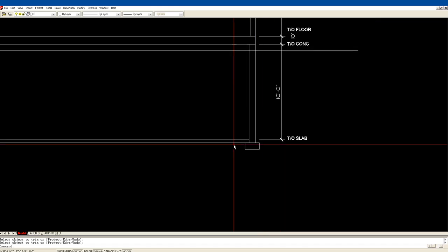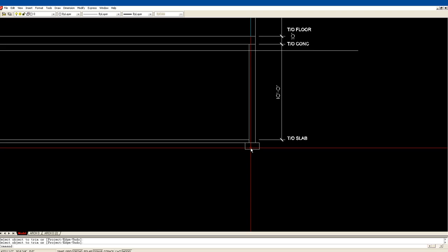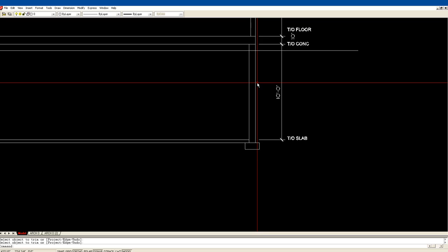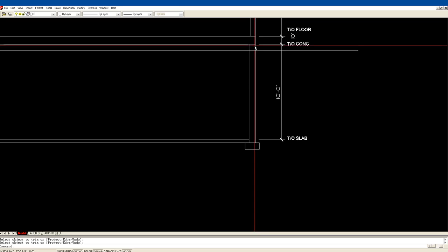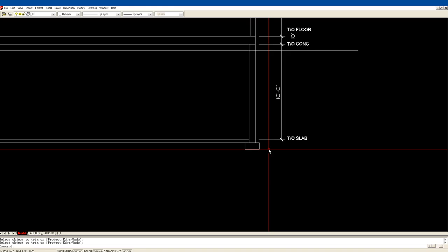So I have a footing, and when we finish off this cross section, we'll show 2 rows of rebar. Again, the engineer is going to change all of this. He's going to make his own drawing, but we're showing 10 feet to the bottom here. We're showing an 18-inch wide by 8 inches thick footing running around the whole building.